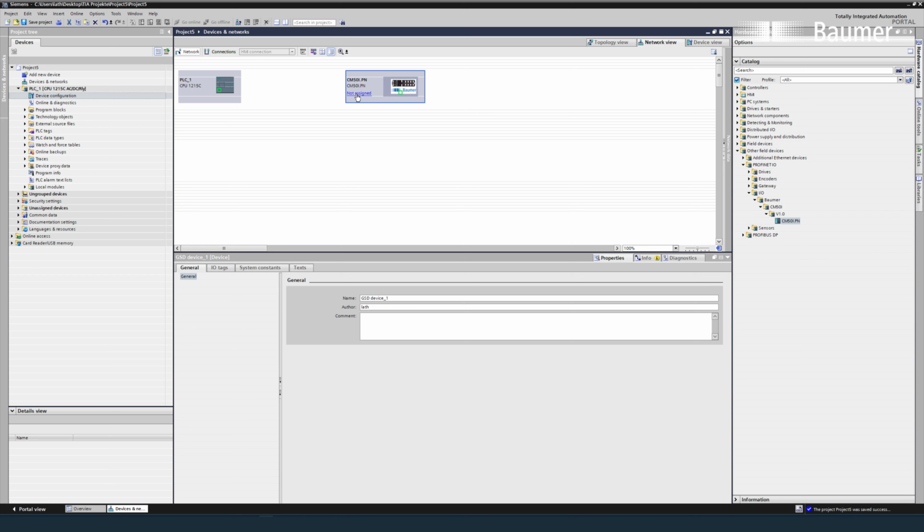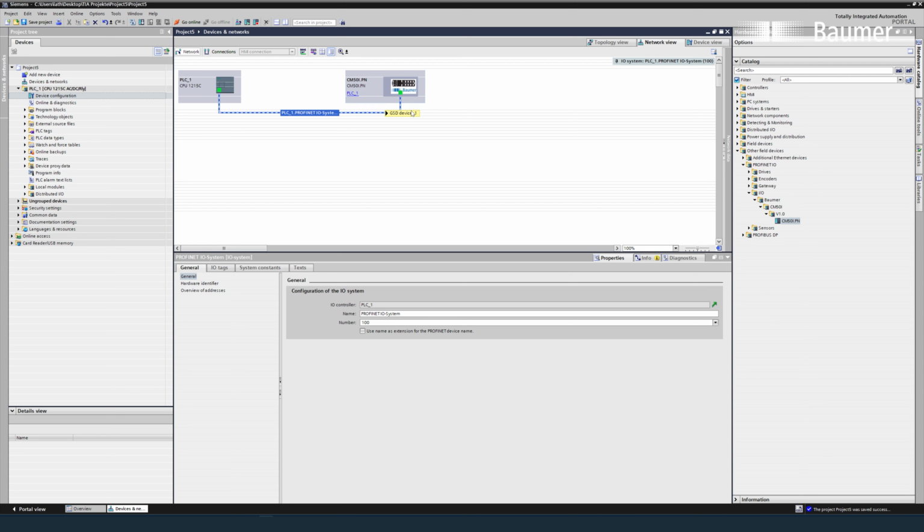Now we click on Not Assigned, and this will allow us to assign this master to the PLC that we just added. And by that, we just added our IO-Link Master here in TIA Portal.